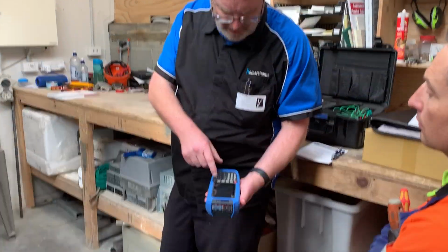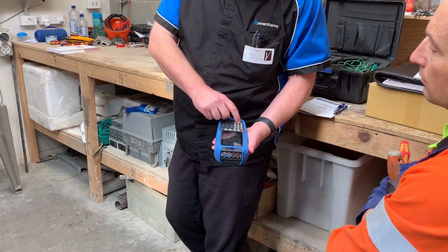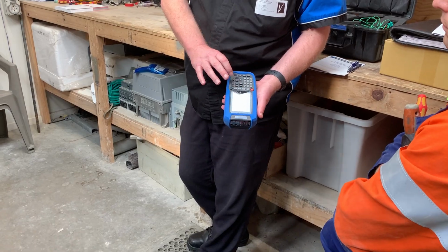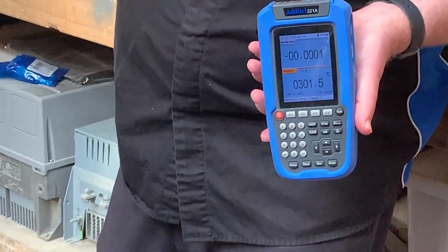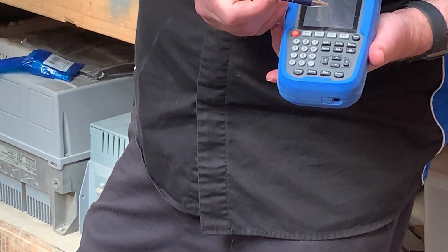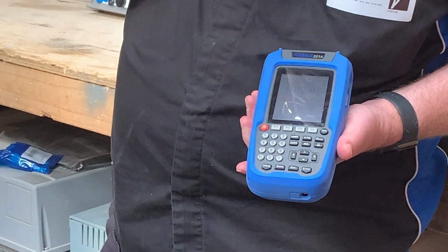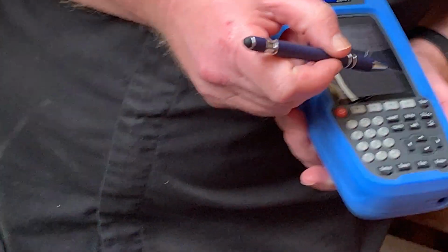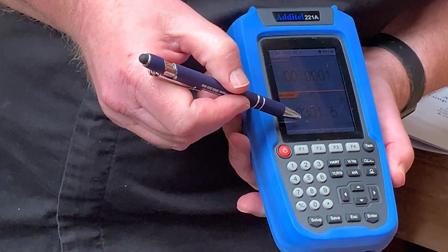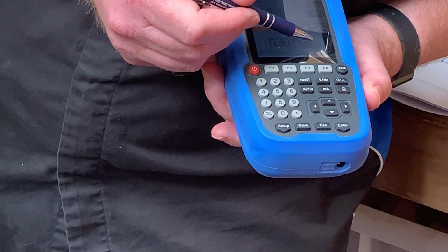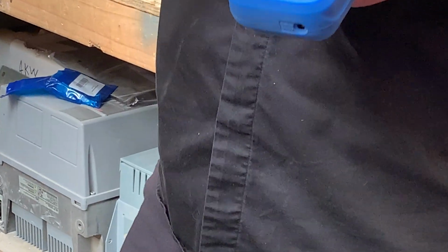So let's say we want to simulate 300, let's make it harder, 301.5 degrees C. So I've just typed that in, enter. Now, coming out of the source terminal is a calibrated 301.5 degree signal as if it was a K-type thermocouple at that temperature. So you can see we've got an internal reference cold junction calibration of 17.25 degrees, and it's at 11.562 millivolts. That is a hand on a stack of Bibles signal.